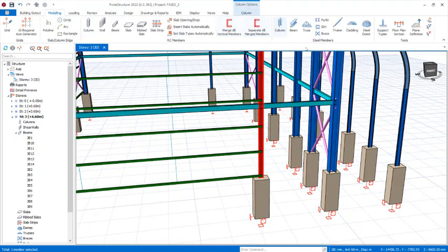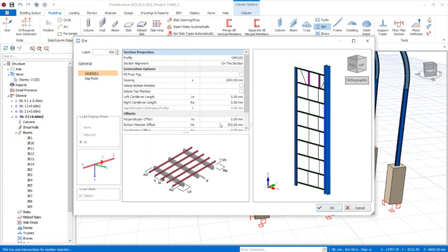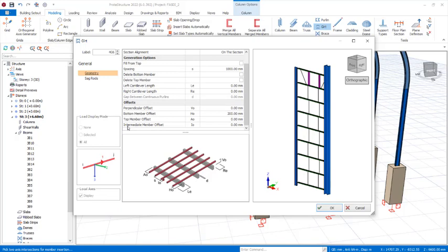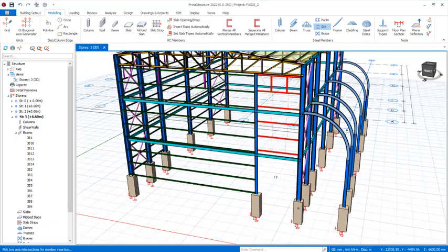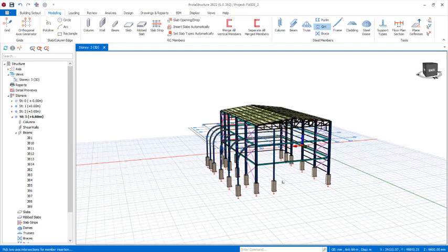Go back to the modeling tab, it's been deselected, get it selected just like this, pick this column and this one. Having this, come to these provisions where you have bottom member offset and then change it to 2000, 3200. Click on the OK option to have this. Okay, this is also an entrance, so we will have another entrance from this back, this provision.